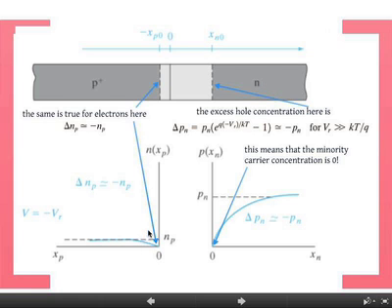So you lose the minority carriers. So in the case of the holes, a p-type, you get electrons here that get pulled across to the other side. So you lost the minority carrier. So you have a carrier extraction, which goes the opposite way. Okay? Now, of course, if you plot the carrier concentration as a function of position, you have the opposite. You have a decrease in the carrier concentration, and then it increases far away to the equilibrium value.